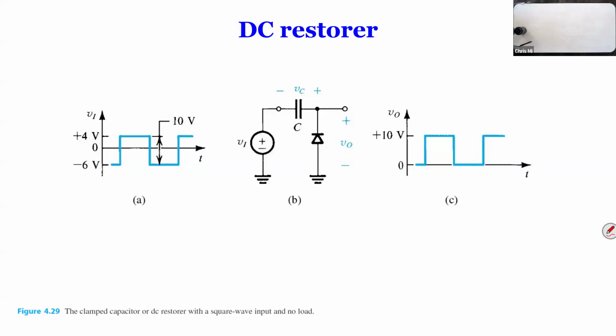Sometimes people say, "Oh, this is not AC, this is a square wave." Yeah, a square wave is AC. Of course, it depends on where the middle is. If a square wave is all above 0, that's not AC. A sine wave is a sinusoidal AC. AC means sometimes positive, sometimes negative, alternating between positive and negative. Regardless of whether it's a square wave, sine wave, triangle wave, or sawtooth wave, it's AC.